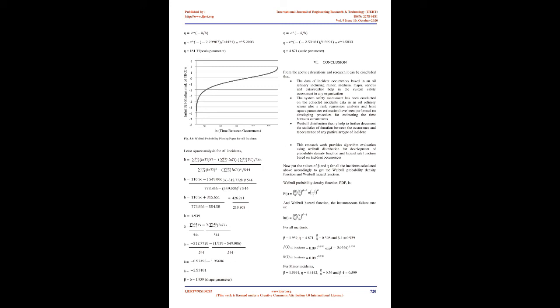The primary advantage of Weibull analysis is the ability to provide reasonably accurate failure analysis and failure forecasts with extremely small samples. Solutions are possible at the earliest indications of a problem without having to crash a few more. Small samples also allow cost-effective component testing. Another advantage of Weibull analysis is that it provides a simple and useful graphical plot of the failure data. The Weibull distribution has the great advantage in reliability work that by adjusting the distribution parameters it can be made to fit many life distributions. It is independent of other variables and uses real-time incidence data, making it more reliable for the study.